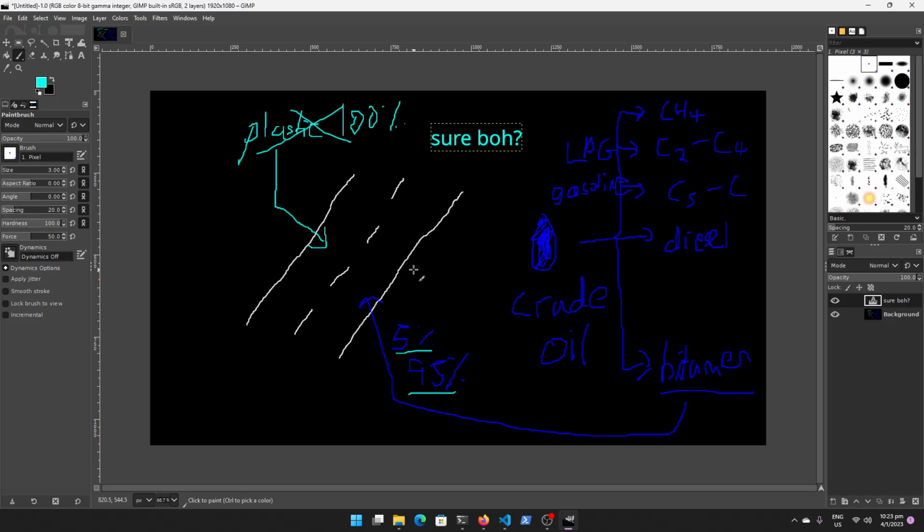So that is the deal with 100% plastic roads. That is not feasible. Why? One thing discussed in the video is that it's too soft. It cannot handle the weight of cars. It doesn't grip surfaces well enough, especially when conditions on the road get icy. Then you'll tend to lose grip easily, and that's a safety hazard. You cannot have that happen. So this is probably not feasible.